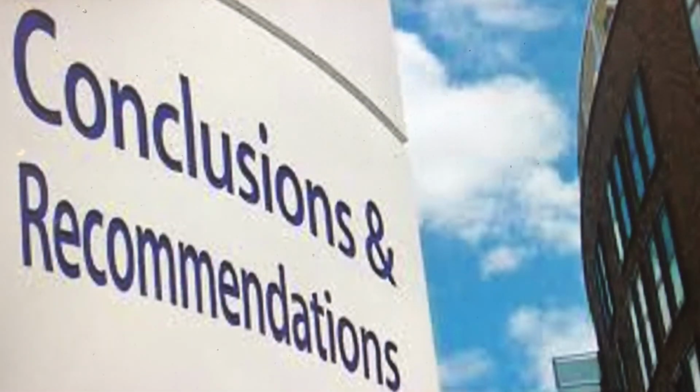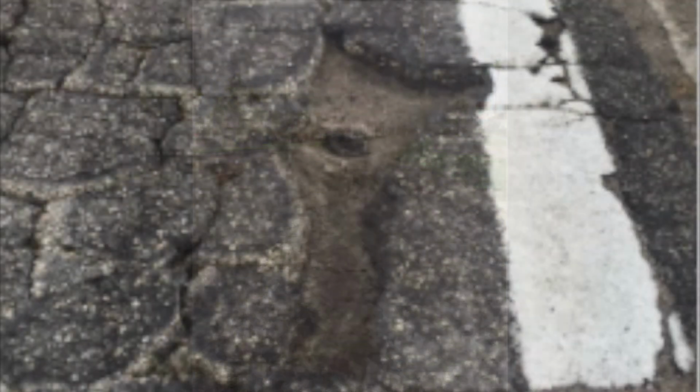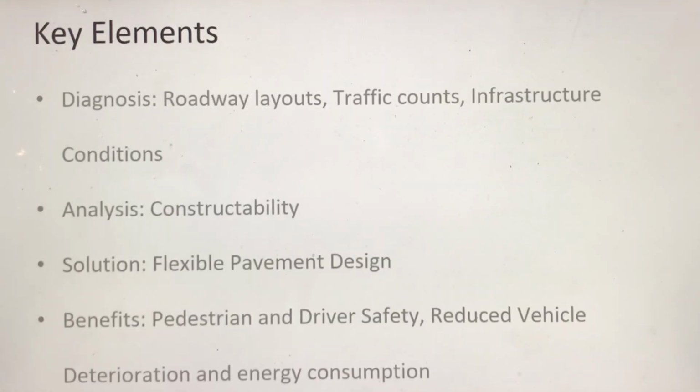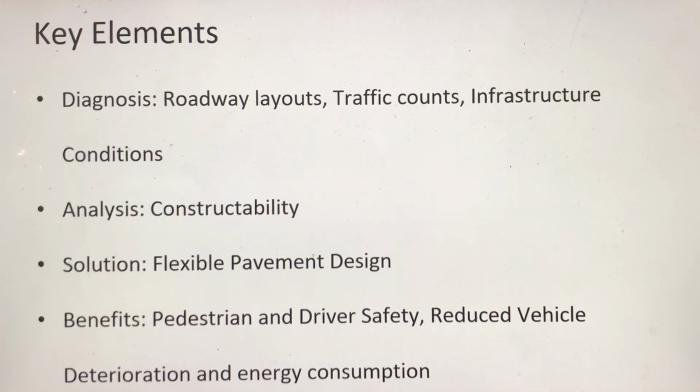In summary, the challenges addressed were severe cracking, delamination, and potholes. The key elements of the diagnosis were roadway layouts and traffic counts; for analysis, constructability; for the solution, flexible pavement design; and for the benefits, pedestrian and driver safety, reduced vehicle deterioration, and energy consumption.